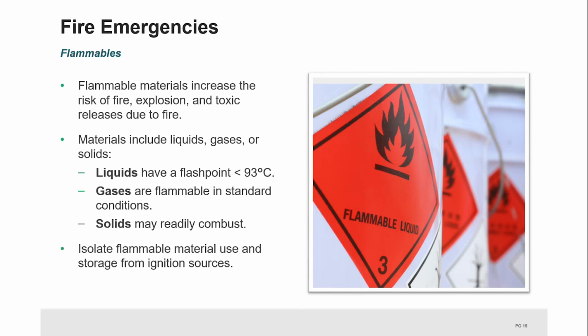Flammable materials present the danger of fire and explosion and often contribute to a toxic environment. These materials include liquids, gases, and solids. Flammable liquids have a flash point of less than 93 degrees Celsius. Flammable gases are flammable in standard conditions, including standard pressure and an air temperature of 20 degrees Celsius, or room temperature.